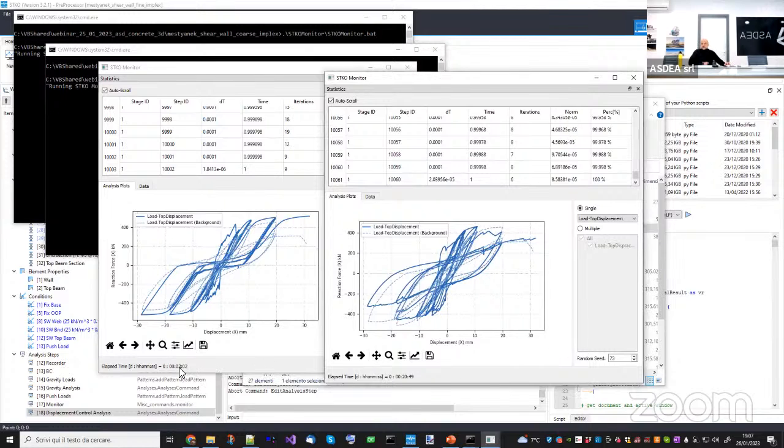The times, of course, increased. It went from 3 minutes to 20 minutes, but you have a lot of elements. But now you have this much nicer amount of plasticity here. Why is this happening? Well, this happens actually due to the rebars. Okay, I will try to explain that to you. So let's go in post-processing.